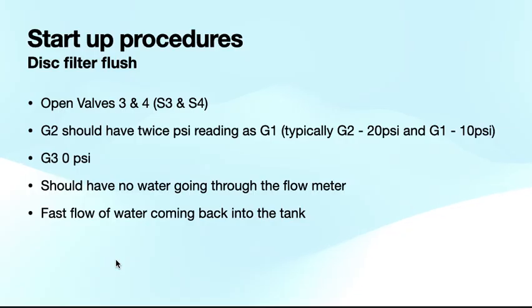That's the dose. All right, the next step in the startup procedures is opening up valves 3 and 4. Before, we just opened up 1 and 2. In this instance, we want the pump running with only valves 3 and 4, or S3 and S4, opened up. All of these things that we're testing are things that the system is automatically doing throughout the day, but we want to test them manually after you do the install to make sure that everything is wired correctly and that the pipe and the plumbing has all been done correctly. It's just a way to double check and really make sure that the system's been installed correctly and it's working. So this is simulating the disk filter flush.